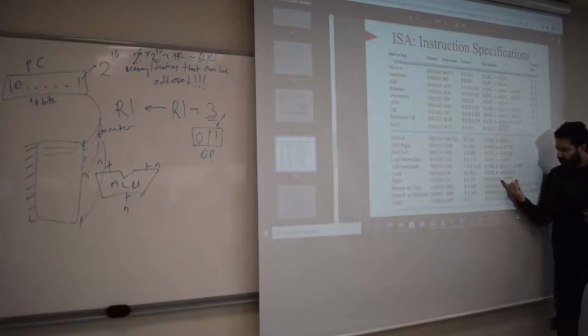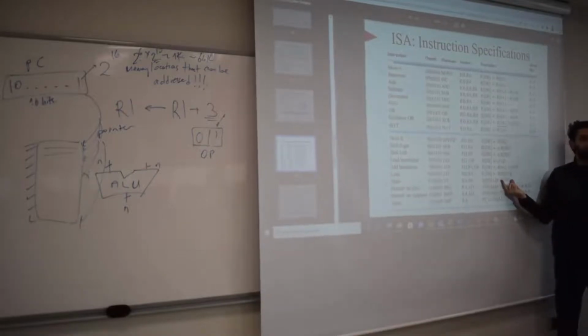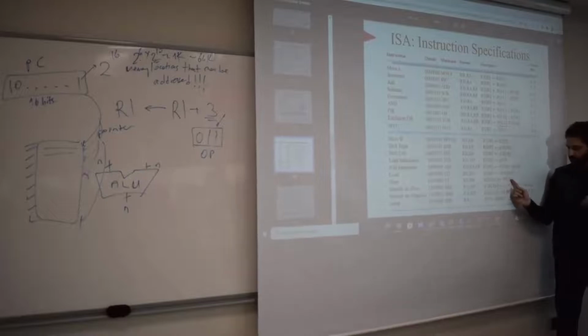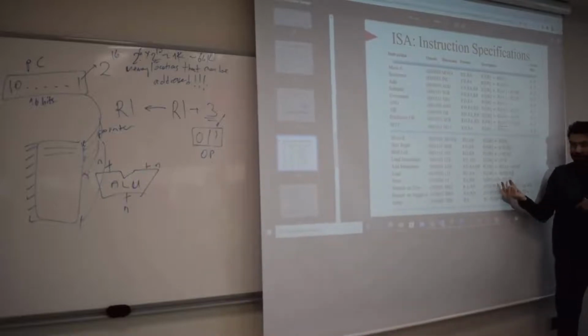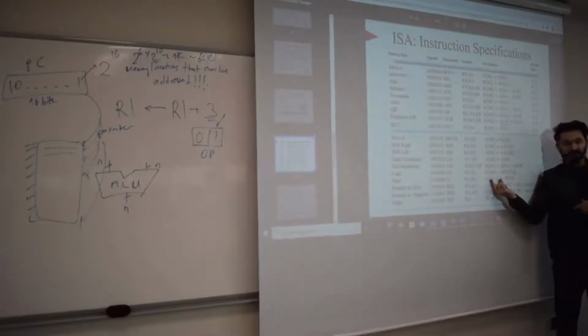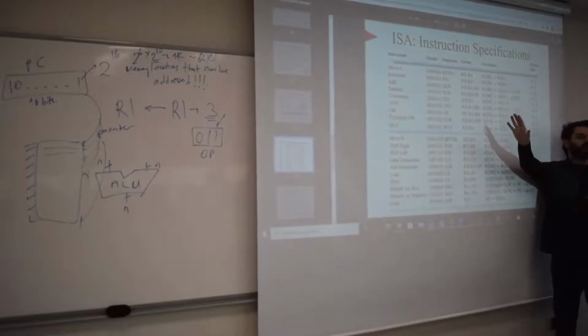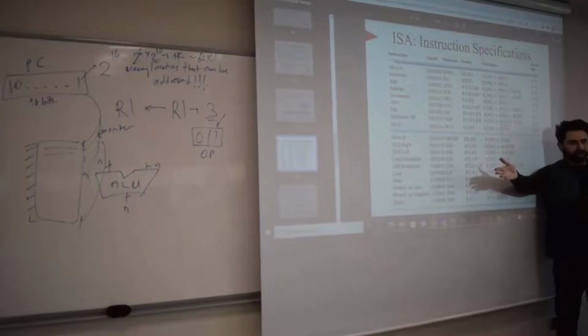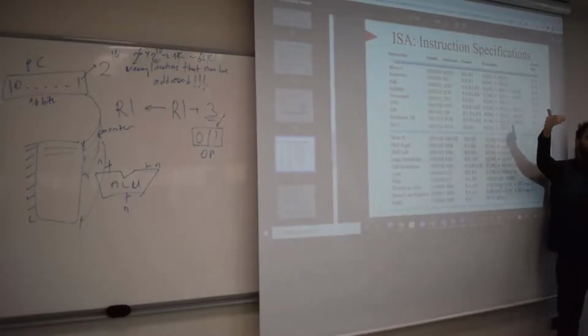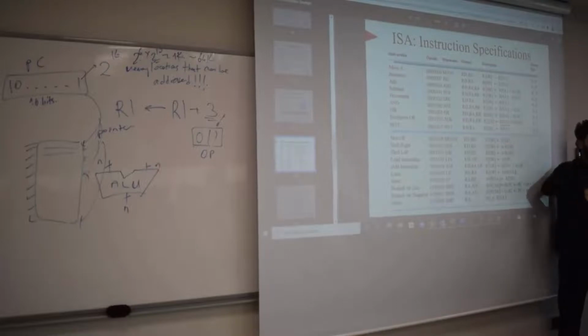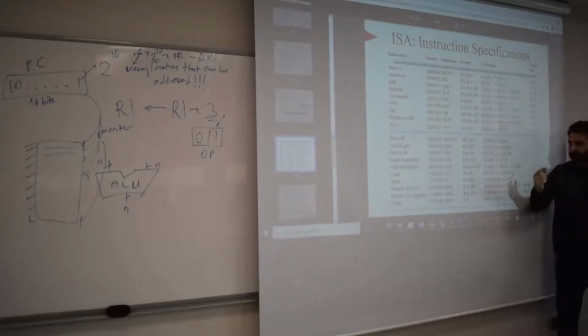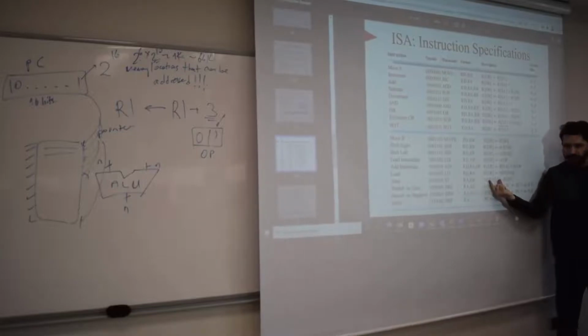So here, what this means is that the register content now in this case is the data that you put on the source B. That's why we have SP actually. And you also have an address that is written in source A. Whatever the register that has the address, for example, R2 has the address, you select that address value and put it on source A, bus A. That bus A now determines your address.